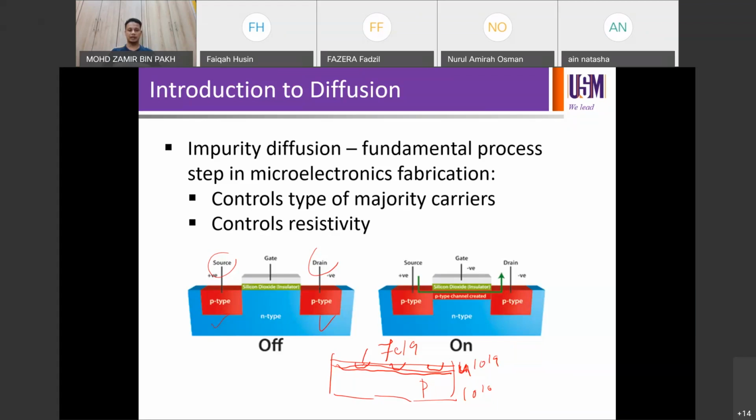But for this particular case, if you talk about CMOS, it's a completely isolated region of p-type, for example, in this page. But all around is n-type, right? Or you may have the silicon to be p-type, but your source and drain can be n-type, but there is no lightly doped n-type. So that's why I say the fundamental knowledge is the same, but the moment you go to your devices, it depends on your device architecture. Either it's blanket, or heavily doped in blanket, or heavily doped in isolation. It can be entirely different cases for different devices.